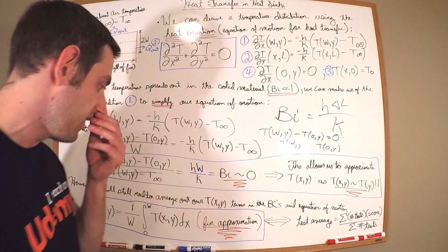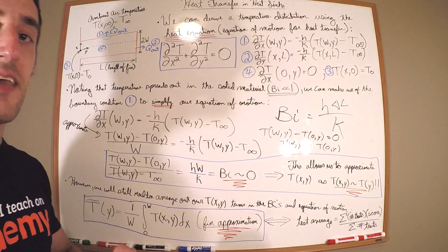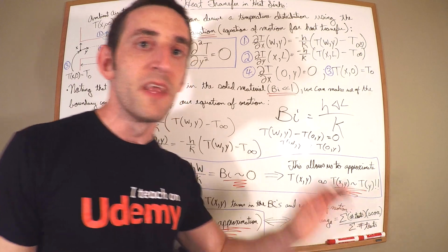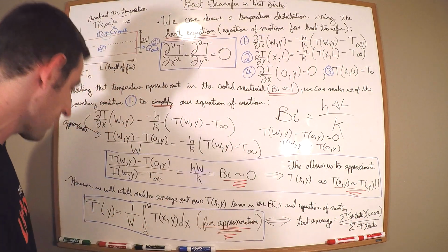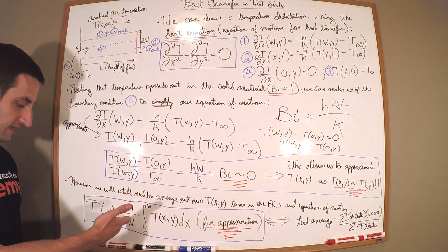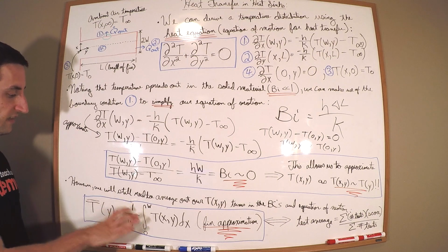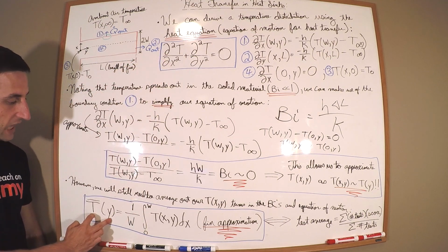So we're averaging it in the x direction. This is very important. It crops up multiple times in heat transfer analyses, heat sink analyses, and so on. This is known throughout the literature as the fin approximation. We're approximating the temperature in the fins by just averaging it over the distance, okay? So if we take this, our T in this equation is going to turn into the following.